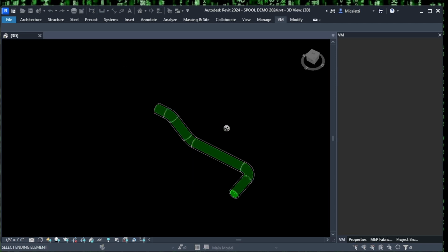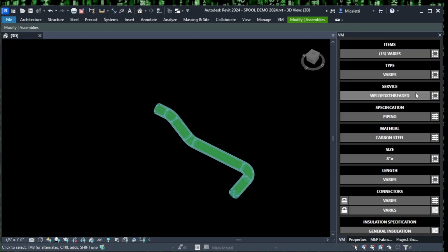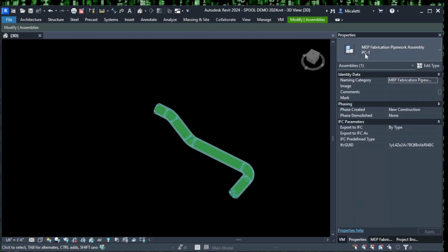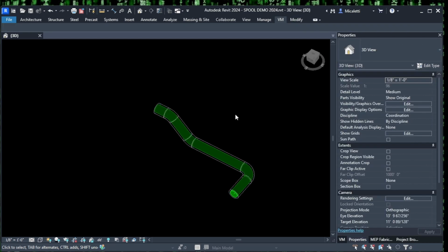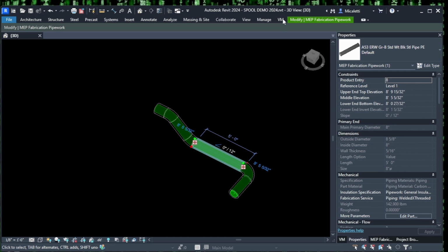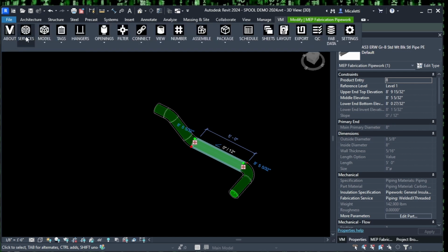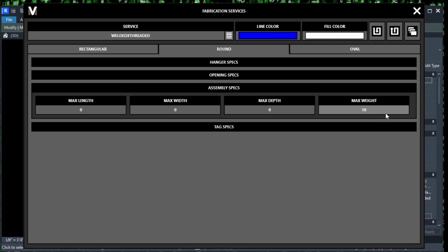Okay, so now, I could continue picking down the line if I wanted to, but I just hit escape. And if we look at this, we can see that's made PC1. Okay. Now let's turn off that ridiculous weight. 0 is unlimited. So we're going to go ahead and say that.